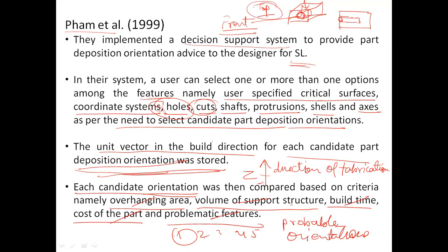So deciding on the proper orientation of the part becomes very critical here. When you are selecting the orientation in order to determine the features, it becomes essential that you observe all the axes, or rather all six views, before deciding on the final view through which you are going to develop the part.